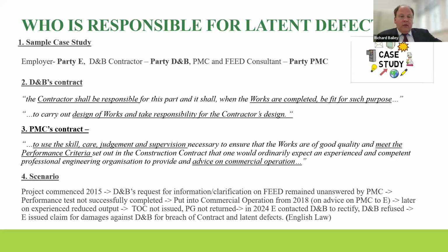And going forward, there's a new 15-year limitation period that's been introduced, particularly for fire safety issues, which would inherently be latent defects if these things are being picked up. So I just want to mention that. The other thing I just want to mention on limitation is that there is actually a difference depending upon what the claim is. So if it's something of workmanship as a contractor, it is either 6 years or 10, 12 years, for limitation from the date of practical completion. But we always have to remember, Lois, that when we're dealing with tortious claims, which are not against a contractor, which are designed so by an architect or an engineer, the date of the arising of the cause of action is actually earlier, at the date that the negligent work happened, whenever it might have been discovered. So we do have to be quite careful around those things.